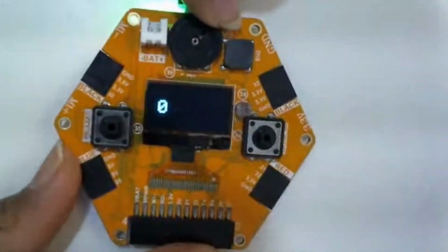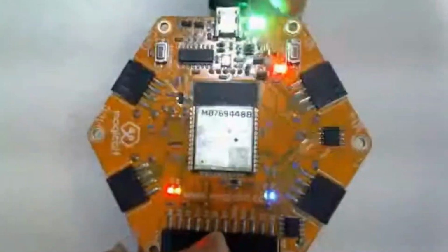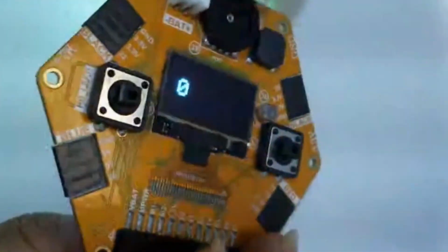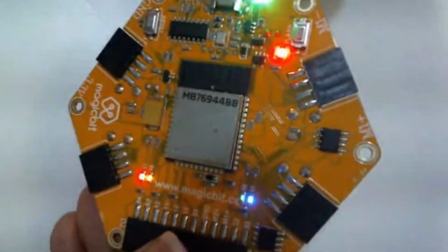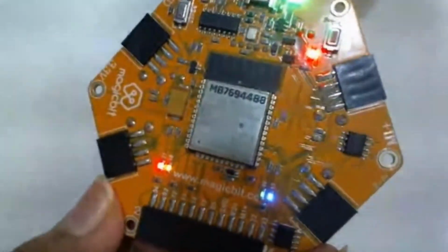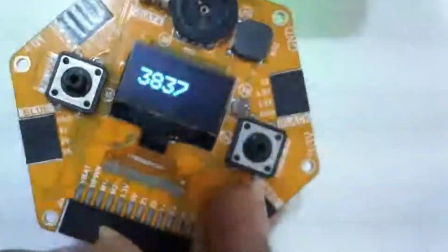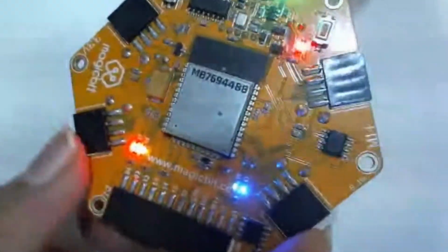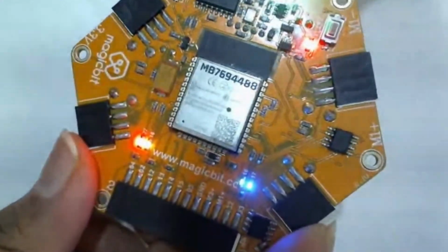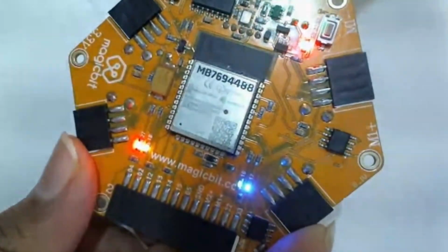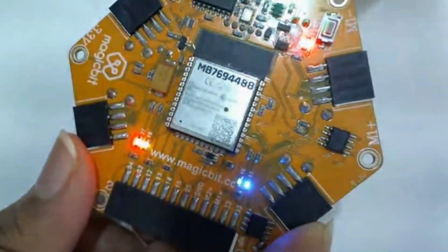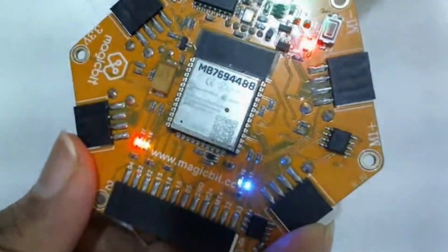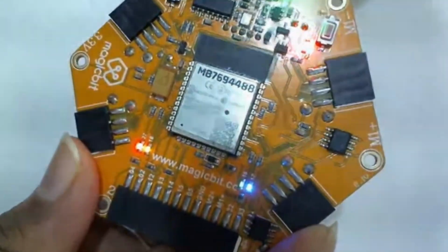Now the potentiometer reading is 0. If we check, the brightness is very low. When we rotate the potentiometer up slowly, you will see the value also getting increased. The brightness is also getting increased. See? Right. Now the brightness is very high because it is greater than 3000. If you rotate it back, you will see the brightness getting decreased. See, one level goes down, another level goes down, and now the low brightness. That means the PWM value is 50.